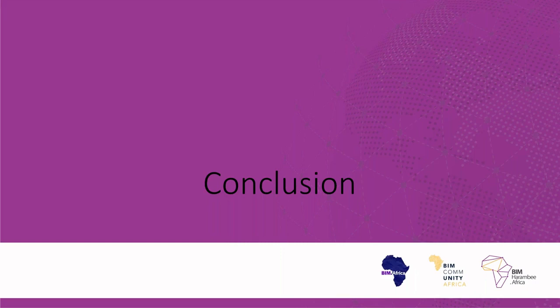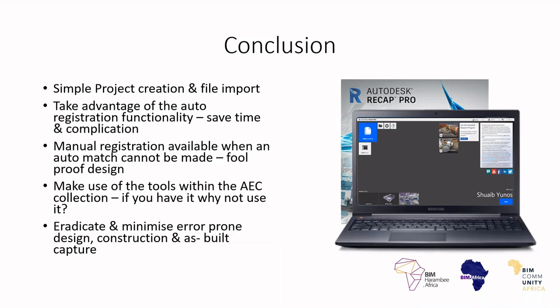So that's it for our instructional demo on Autodesk ReCap Pro for point clouds. I hope it made sense. Just to recap what we've done, recap, right? No pun intended, actually. We created a project very easily, and then we imported it based on the settings that we had set. We then took advantage of the auto registration functionality, which saved us time from manually registering each and every scan. We were left with, I think, 2 scans that we needed to manually register, right? It allows for foolproof design because when the software cannot process it, human intervention is required, and you can actually